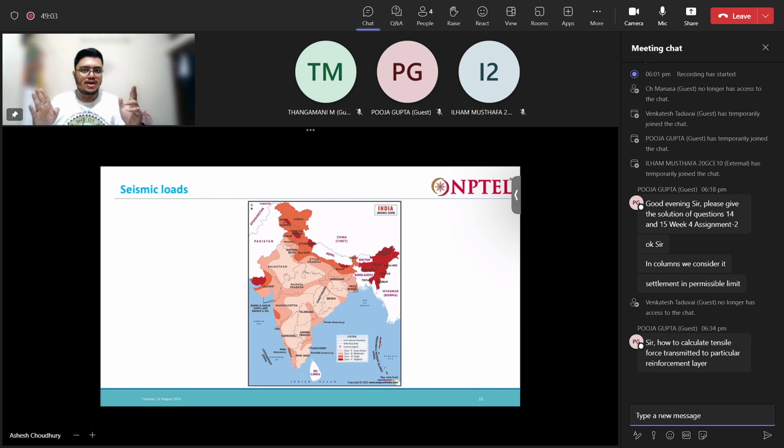Our main task is to determine the length of the reinforcement. That will be first the length inside the failure wedge and then the embedment length. To determine all these lengths and the spacing of the reinforcement, we need to determine the force transmitted in each reinforcement.